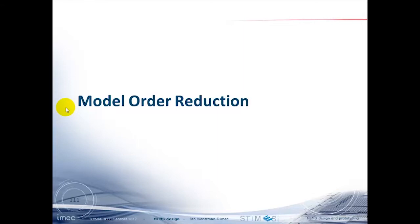But if the blocks are available for what you need, it's still the fastest, most efficient way to do it. And again, you have to be careful. You have to know what the building block models. Like in the case of the gyroscope, you can set up the frame as a rigid body, but you can also model it as a flexure body. It costs you a lot more time to make it a flexural body. And in the end, instead of making a geometry which you mesh into smaller parts, you start with building blocks to make a full structure, but your building blocks are becoming smaller. In the end, you may be meshing with better models.